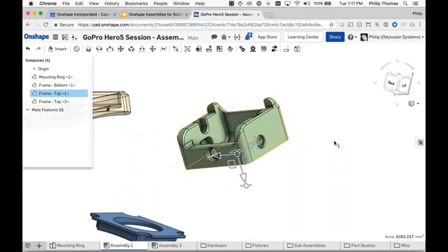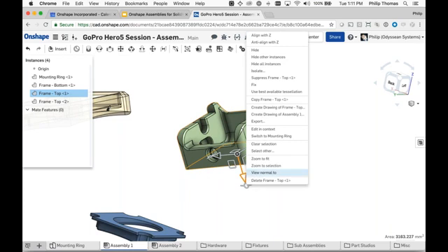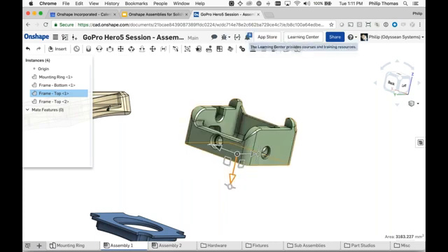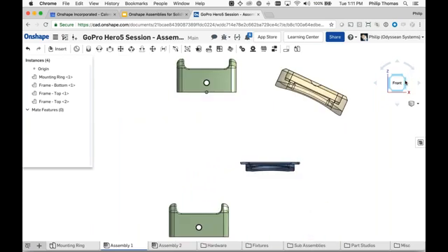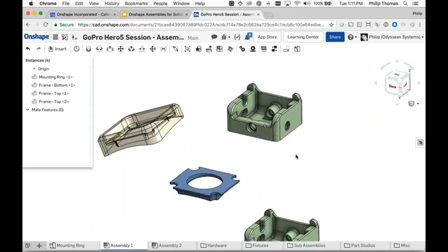Now I still don't have this frame top part aligned with the primary axis. It actually doesn't matter, but let's go ahead for neatness sake, align this so the front is front, left is left, and so on. So by right mouse buttoning over the arrowhead, you have the same align and anti-align concepts as exist in SolidWorks when you're creating a mate, right? Remember the 2 options, align and anti-align. In this particular case, I'm going to anti-align with Z, and now I have aligned this part with a center on the origin and oriented it relative to the other parts. There was no mate, I simply positioned.